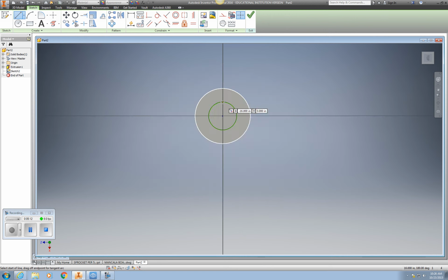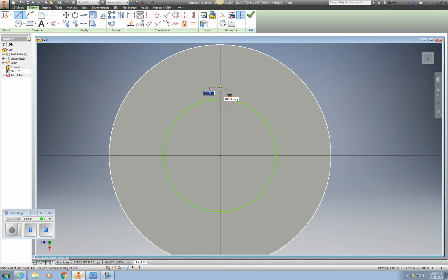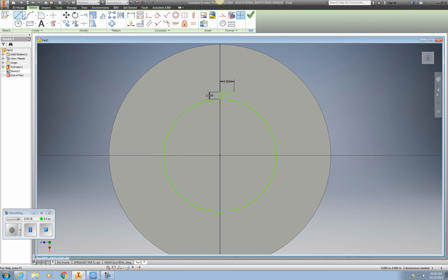And we're going to start at the top quadrant. I'm looking for something that references that keyway, and I see a leader line pointing to it, 8x2 keyway. Now, if I'm looking at the dimensions, that's telling me it's going up 2 vertically from the quadrant, and then to the right, 4 horizontally. Then hit escape and come back with the line command once again, to the left 4 for a total of 8.